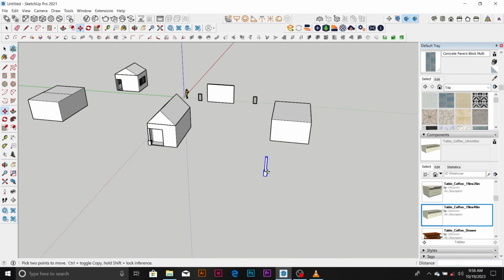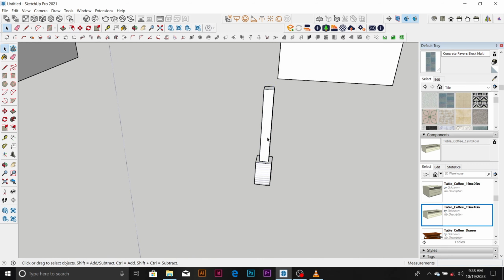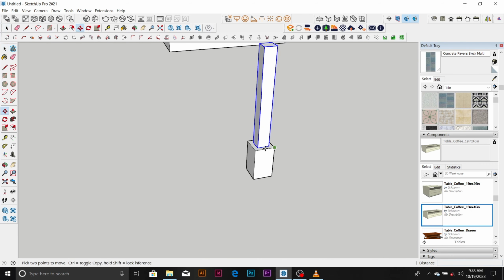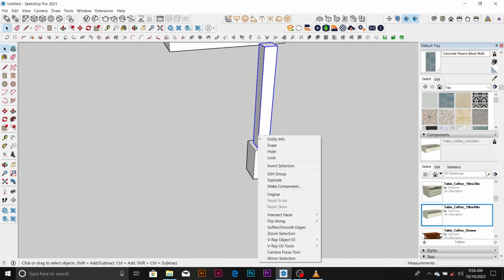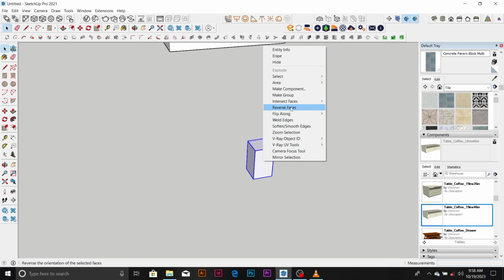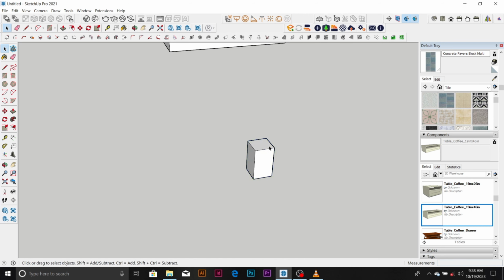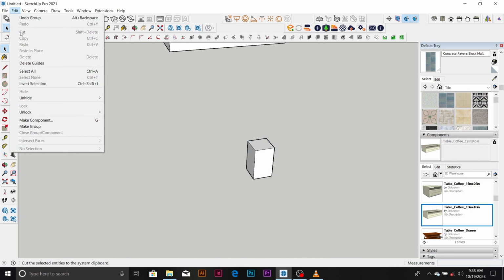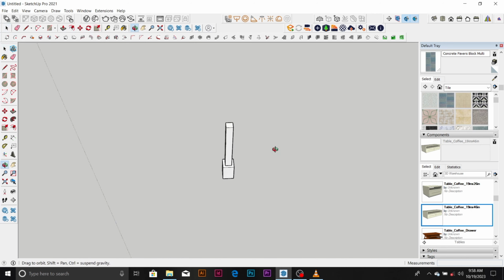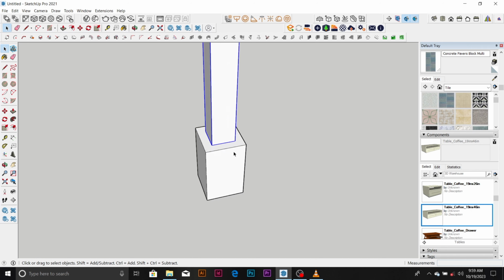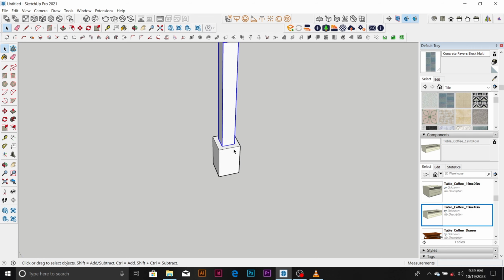Okay, this drawing now. Hide. I want to hide this thing. I want to make this one group. I want to unhide it. Come to this edit, unhide last. Unhide last. So this group now enables us to maintain clean geometry. Try to be grouping your work. I've taught you how to group. Try to group your work for you to maintain a clean geometry.